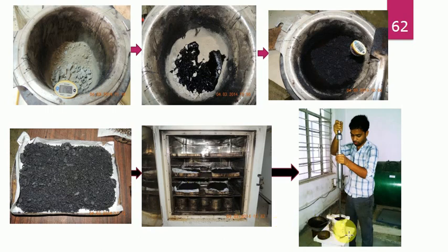So here this is the mold, and you have to do the compaction as specified by the test method, that is either 75 or 50 or 35 blows. After that you have to rotate the mold and again apply the compaction.